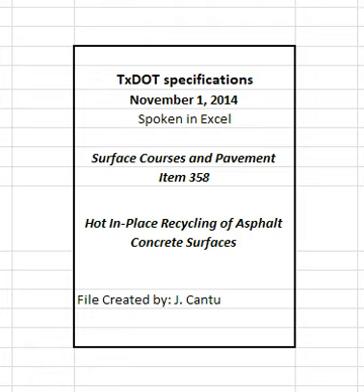4.5 Addition of recycling agent. Incorporate the asphalt recycling agent into the hot recycled bituminous material at the rate determined by the approved mix designs. Sampling and testing during mixture production may result in varying quantities of recycling agent at different portions of the project to meet the requirements in Table 1. Change the recycling agent content only as approved.